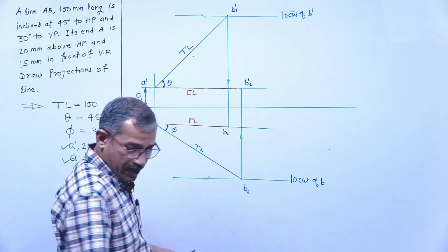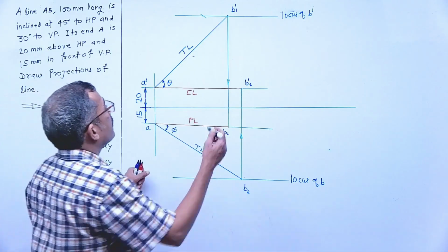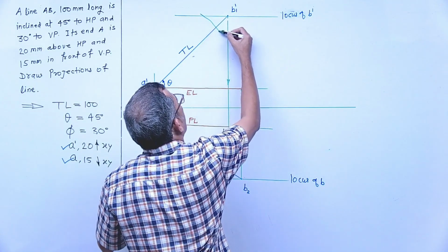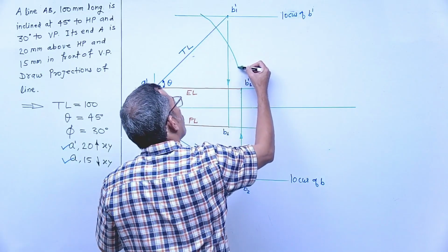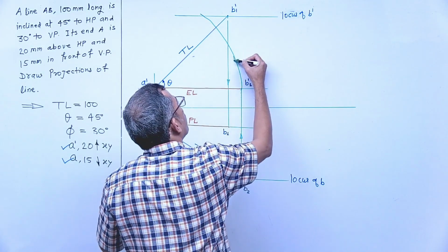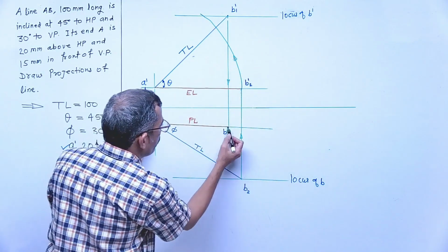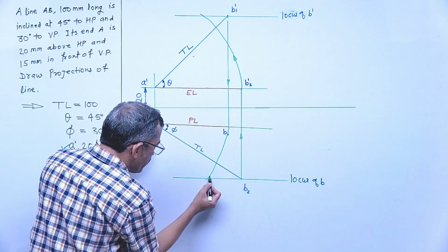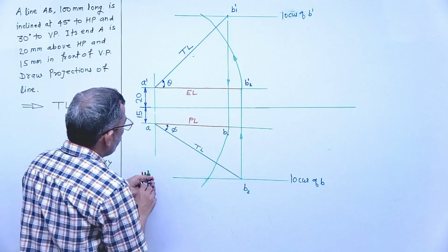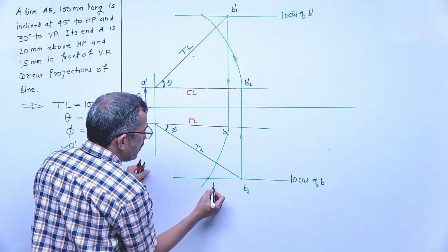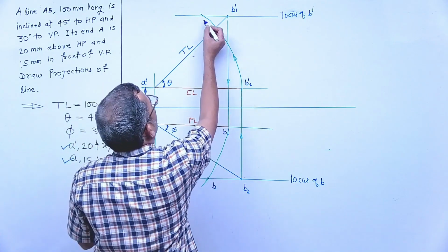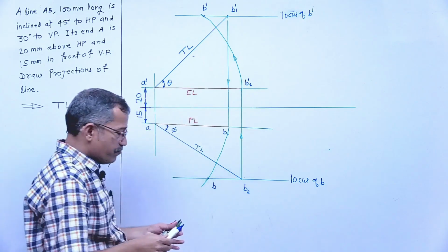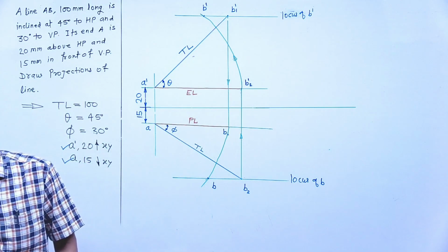This arc, you can draw it like this, right? This is your arc of radius EL. This plan length, when we rotate it, will get what? One arc, right? Which passes through this point. What is the name of this point in top view? When we rotated the plan length, B came. And here what will we get? B dash. Now the final step, simply join these points.